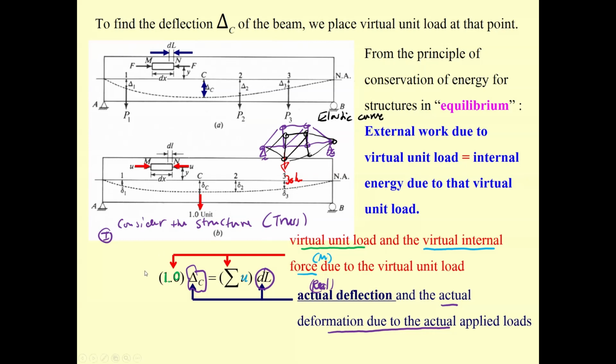You would like to determine, for example, the deflection over here, let's call it V sub C. Then you have to separate this truss into two trusses. One is the truss subjected to the 30 kilonewton, with a pin and roller subjected to this force of 30 kilonewton. And then you take another truss, the same one.